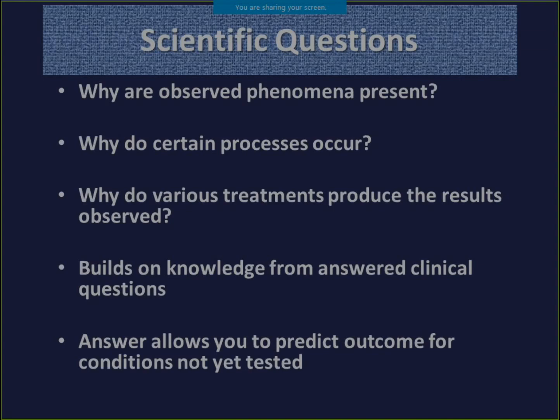Scientific questions might be something more like, why do some coatings hold up better in this particular environment over time? What do they have in common? With these types of questions, we can then predict future coating performance better. We can gain knowledge about the underlying reasons for the observed behavior, not just observed behavior. For example, if we try to answer the question, why are some silver coatings permeable to hydrogen sulfide, so the silver turns black, while others aren't, we can then use that information to select appropriate coatings for future testing.